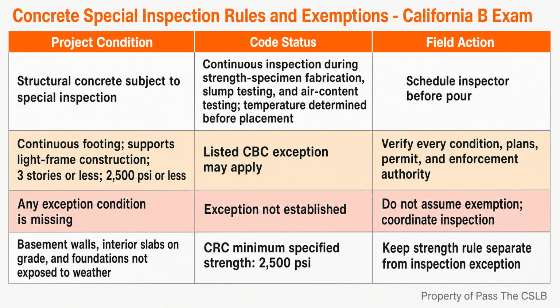California safety orders require falsework and shoring that support concrete to be designed for a minimum total design load of 100 pounds per square foot for combined live and dead loads. The minimum allowance for live load and formwork is 20 pounds per square foot in addition to the concrete weight. The exact design remains the responsibility of qualified parties. The General B responsibility is to make sure the required design, inspection, and certification are in place before loading the system.